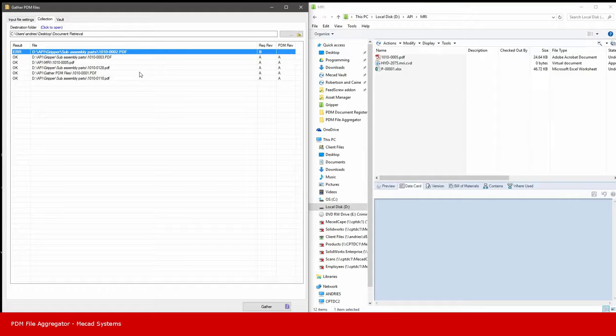Now there are some caveats with this particular search algorithm that I use. And that is that the file vault must have unique file names. If you do not have unique file names, the search will search through the entire vault, and the first file that it finds, which matches the inputs, will be returned. So if you do not have unique file names, basically only the first search result will be returned.